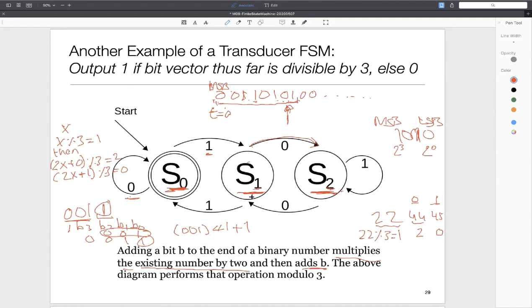So in software, we don't think about the percent operator in my programming language. It's basically just a simple operator, an instruction in the machine. But when you are thinking with a hardware mindset, and designing a chip or an FPGA, then there is a huge difference between a percent operator, because a percent operator requires division, versus applying some smarter algorithm to it. So any question on this slide?